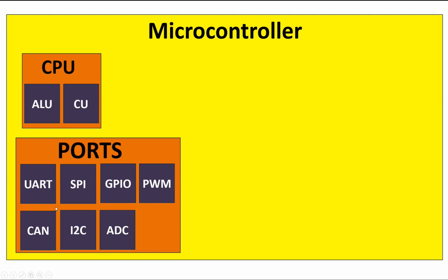Now behind each port, like for the ADC port, for the sensor, like you want to connect a sensor, then you have an ADC module in the architecture of the microcontroller. So the ADC module will perform all the necessary operations for this port to operate, and then its output will come through this port. You don't have to worry about the module, it is inside the architecture. The only thing you care about is the pins, how many ADC pins you have and what is the resolution, etc., and that further specs like resolution etc. go to this ADC module that is built in the microcontroller.